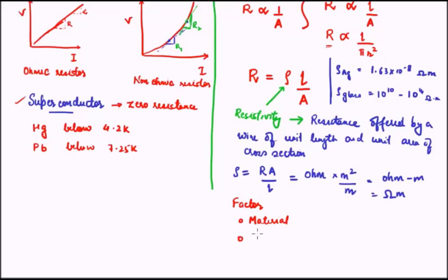Second is temperature. Now the temperature factor is interesting, as in for a conductor with increasing temperature, resistivity increases. Therefore, with increasing temperature, the resistance will also increase.